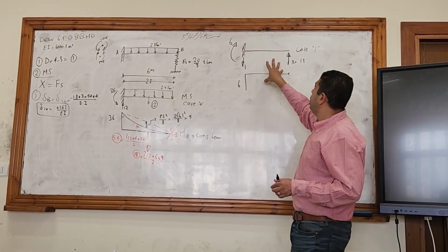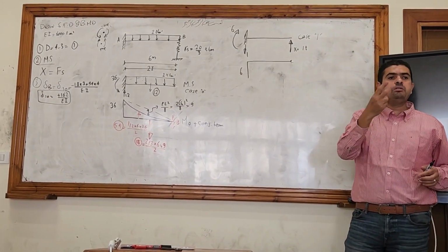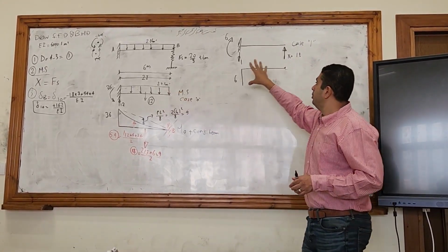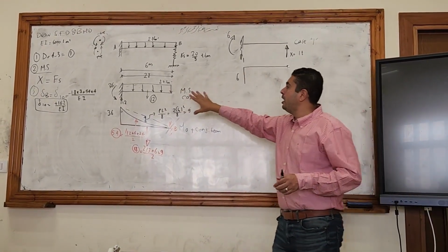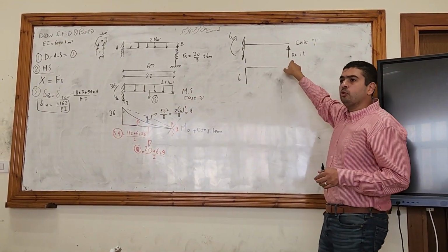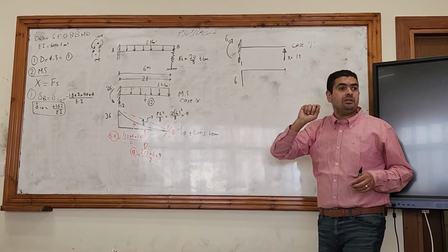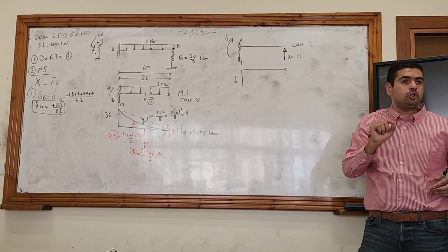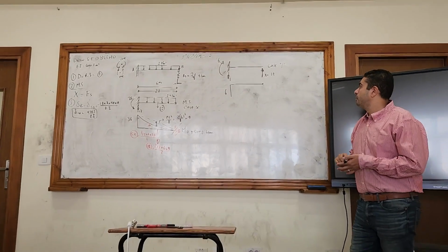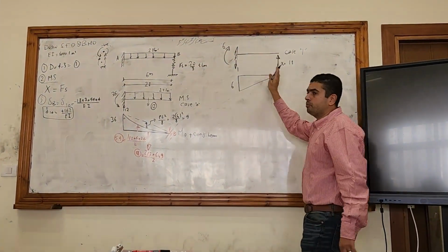If I took the loads here in case 1, that means I took the load twice. Here I took the loads, so no loads here. Here I didn't consider the vertical support, so here I have to consider the vertical support. And I made an assumption that its reaction is equal to 1. It's not equal to 1, it's just an assumption. And the bending moment will be a straight line, no uniform load.